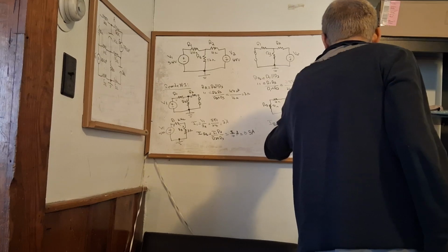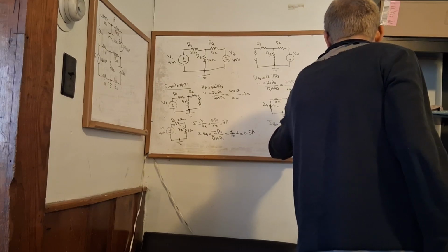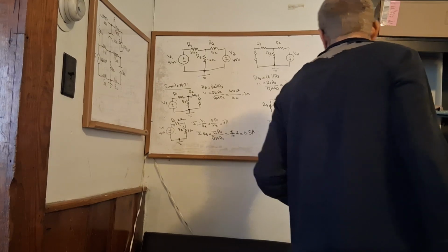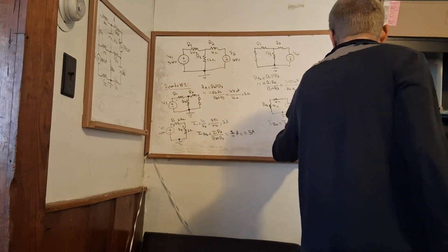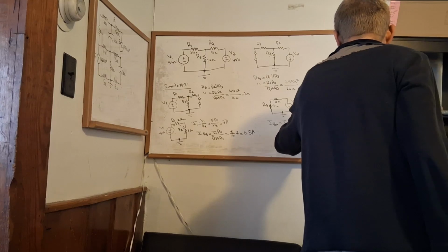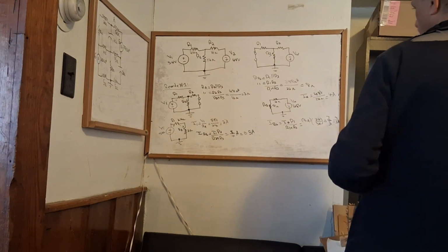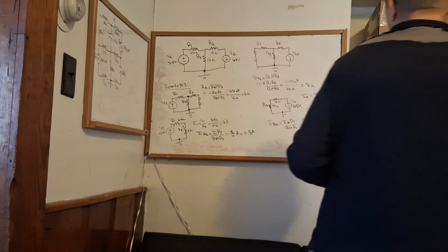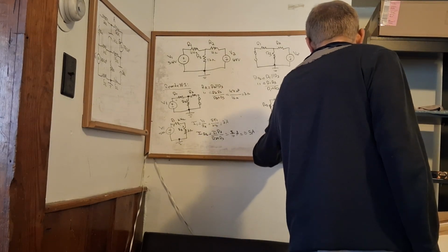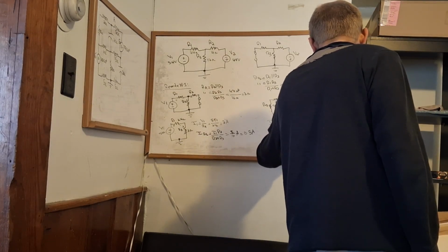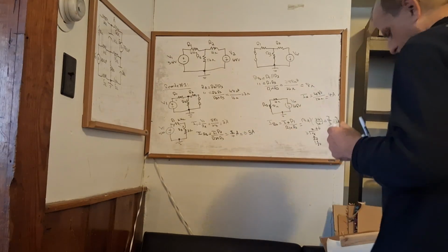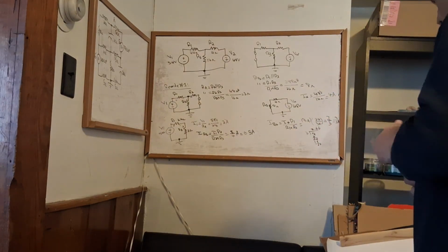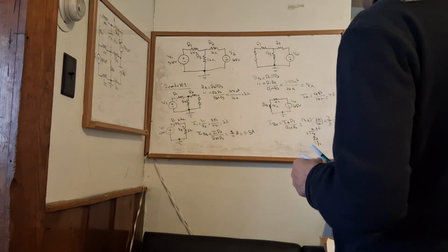over 24 over 36. That's actually equal to 2/3. So 8/3 of an amp through RB. And if we take 3 into 8, then we get 2, that's 6, 2 down, 6, 6, 18.66. Yeah, it's about 2.67 amps flowing through RB.